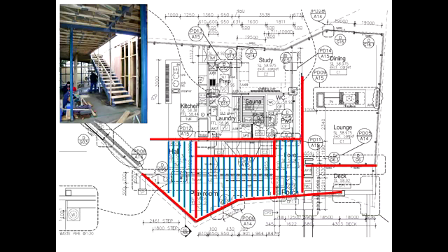But this is more or less what you need to look at when you meet a skylight or a stair. So the first thing you want to look at is the direction of the joists. If the opening is running along the direction of the joists, you're lucky. It's not particularly complicated, but it just means that you've got a couple of extra elements that are used to restore the structural continuity of the floor structure. All right?